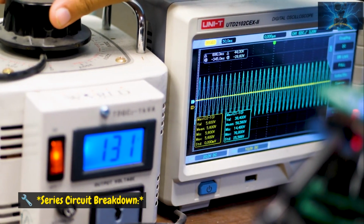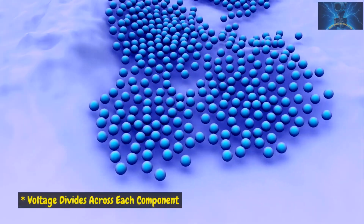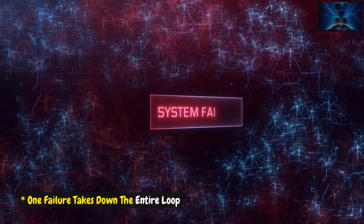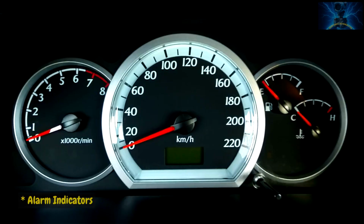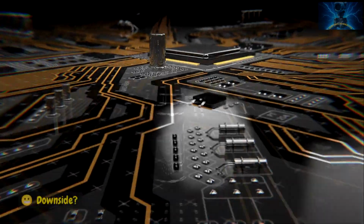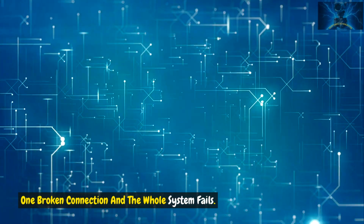Series circuit breakdown. One path, shared current. Voltage divides across each component. One failure takes down the entire loop. Common uses: e-stops wired in series for fail-safe control, alarm indicators, overload relays, and safety chains. Downside: one broken connection and the whole system fails.